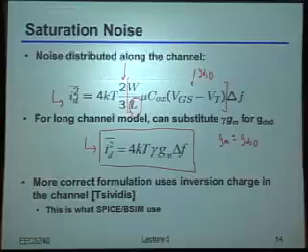So if I keep the drain current fixed, and I increase the L, what's going to happen to the size of the device? In other words, what's going to have to happen to the width of the device? Well, okay, it's going to go up. That's right. So if I double the length, then to zero order for the same current, I have to double the width, right?